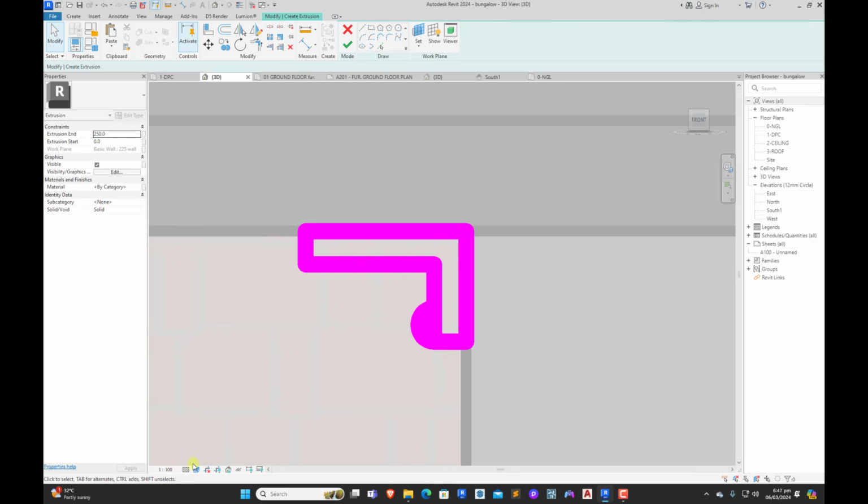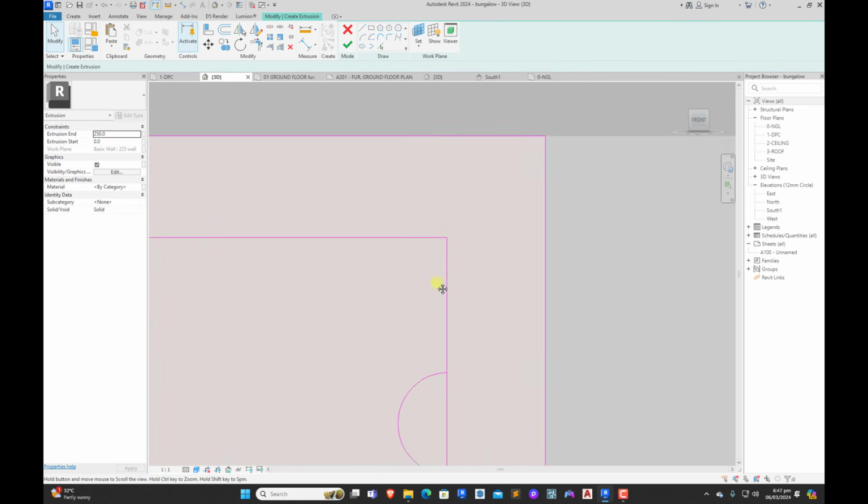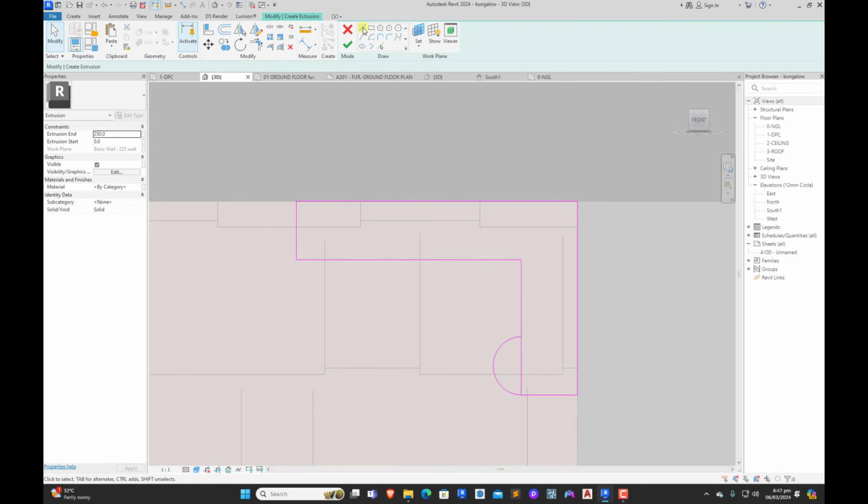And you can see it's very thick, so you can't even see what's going on. So we'll just change this to scale 1:1, so we can be able to see what is happening. We'll also do the same thing here. We click on this, make this 30, and we increase this here. So we can trim this way, and also trim this way.